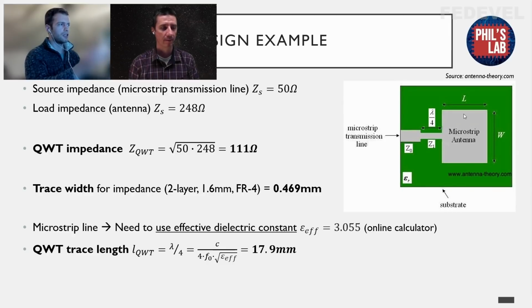But because this is considerably narrower, we need a lower one, and that is the annoying thing about the effective permittivity. You can't just say, okay, we have this much; you have to say we have this much air and we have this much dielectric medium underneath. So that's why it depends on the width, and what makes this whole effective permittivity thing quite annoying to calculate. But yeah, we actually get quite different values. So from 4.17 to about 3.1 is quite a jump.